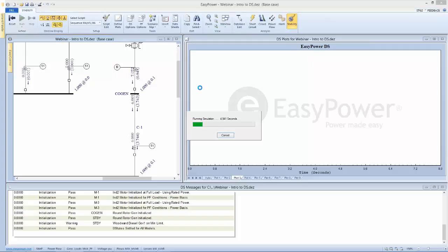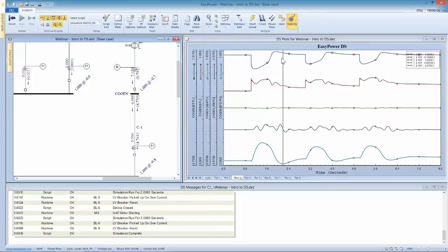So as we run this simulation, it's responding in kind, and as we're looking at the cogeneration terminal voltage, you'll see that it droops when we see the load come on, the motor come online, and then it actually overshoots the system voltage before it's brought back down, again being driven by the cogen field control. You can see it overshoots, comes back under the quiescent point, responds again to the next motor coming online, and again it's what you'd expect or what you would hope to find.